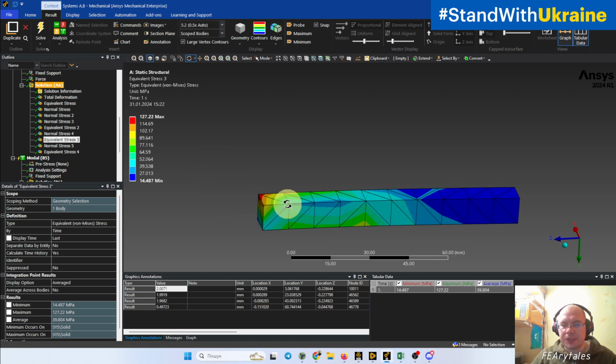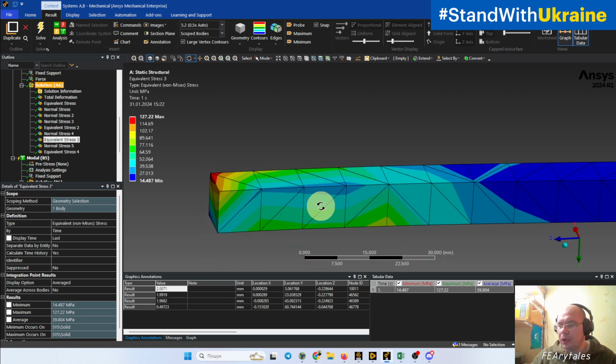It means that we take stress from all elements around the node and obtain a mean value with different algorithms for these nodes. Then we draw this picture which changes stress linearly from one point to another. So it looks more affordable and more accurate.